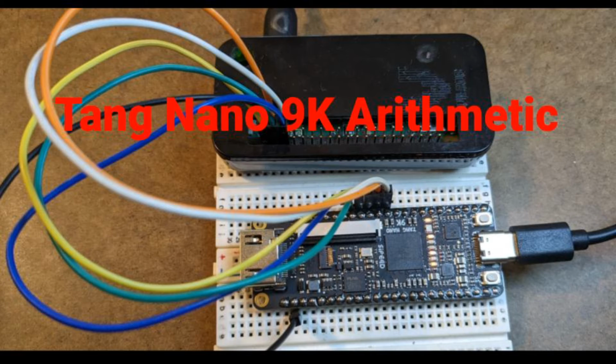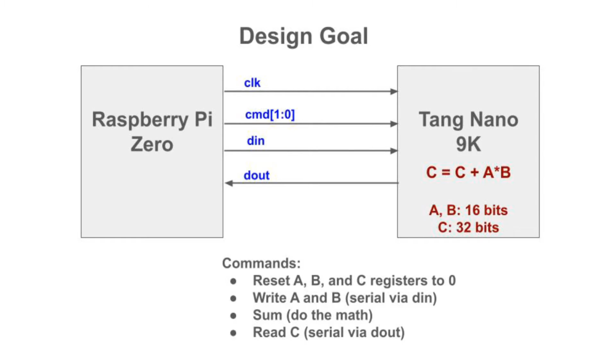In this video, I'll try multiple Verilog modules, hardware arithmetic units, simple serial communication with a Raspberry Pi, and both combinational and sequential logic. My design goals are to have the FPGA implement four things: 3 registers, A, B, and C, to be able to reset the register values to 0, to implement the math operation C equals C plus A times B, and to be able to serially write to A and B via a data in signal and serially read C via a data out signal. These will be controlled by a clock and 2 command signals driven from the Raspberry Pi.